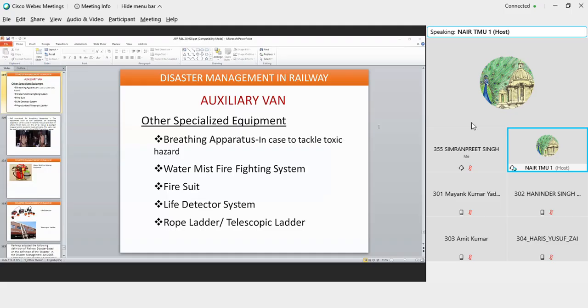But I have to pick up an 80-ton loaded wagon. Then I start using counterweights. If you remember the torque diagram, the clockwise and the counterclockwise, I try to balance by adding additional counterweights on the tail of the crane, so that I am able to lift loads even with limited outrigger propping.